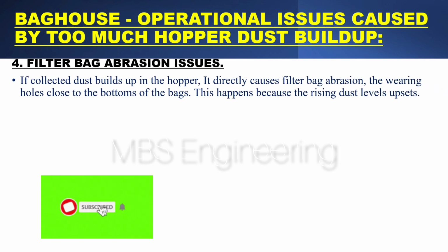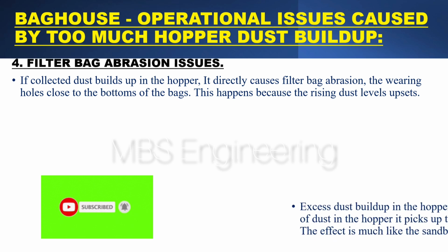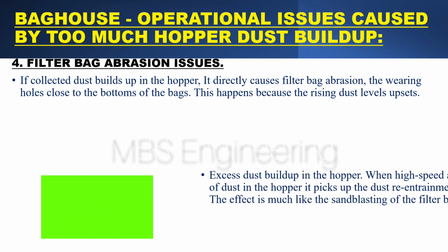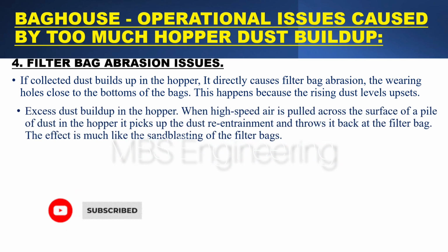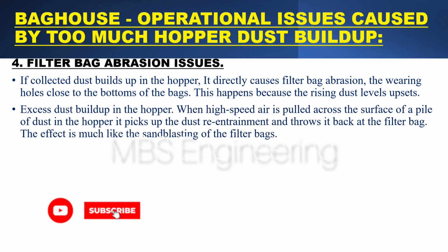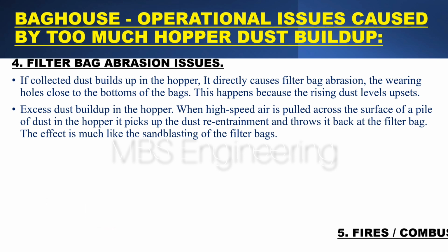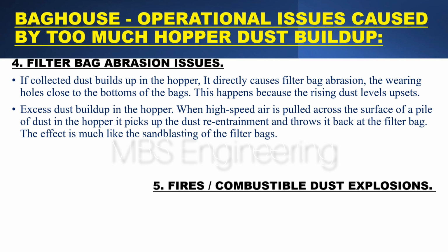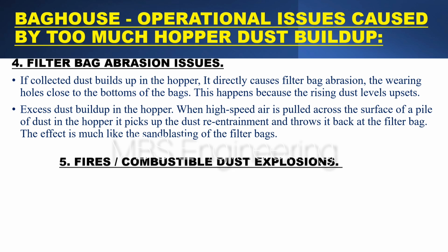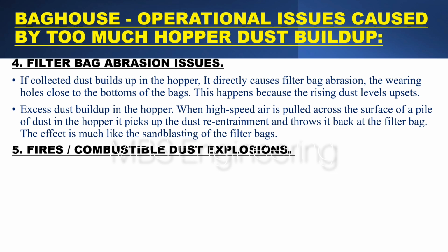Next, the fourth issue is filter bag abrasion issues. If collected dust builds up in the hopper, it directly causes filter bag abrasion, wearing holes close to the bottoms of the bags. When high-speed air is pulled across the surface of a pile of dust in the hopper, it picks up the dust and throws it back at the filter bag. The effect is much like the sandblasting of the filter bags.